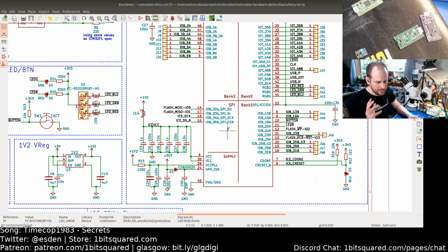That's not strictly correct. I heard rumors, and I don't have this 100% confirmed, that the bitstream loading circuit actually skips completely fused bytes. I'm not sure if it is fusing to 0 or fusing to FF, but whatever the value is, it will skip those bytes until it hits something else, which is a header for the bitstream.